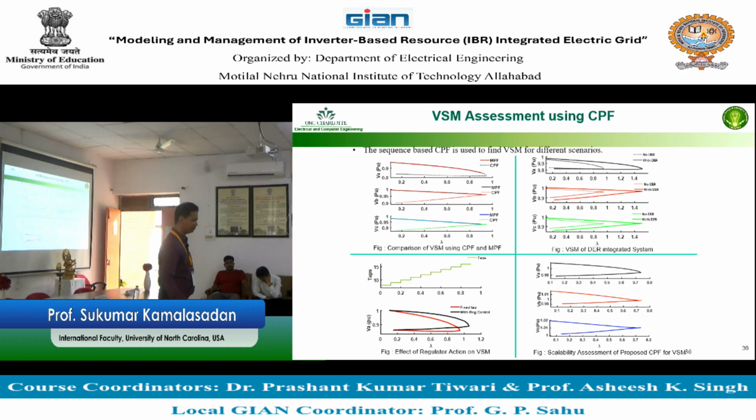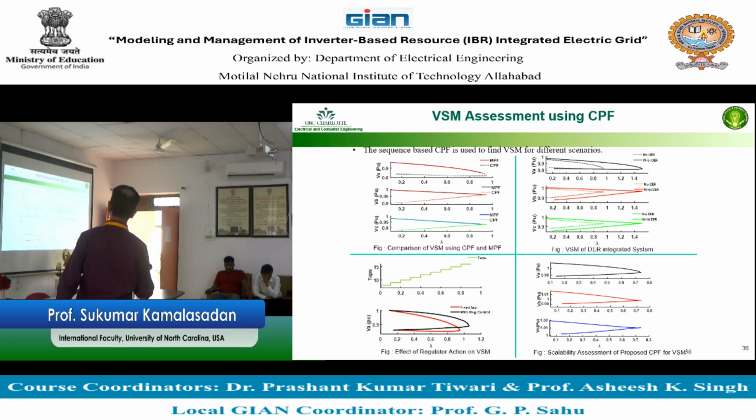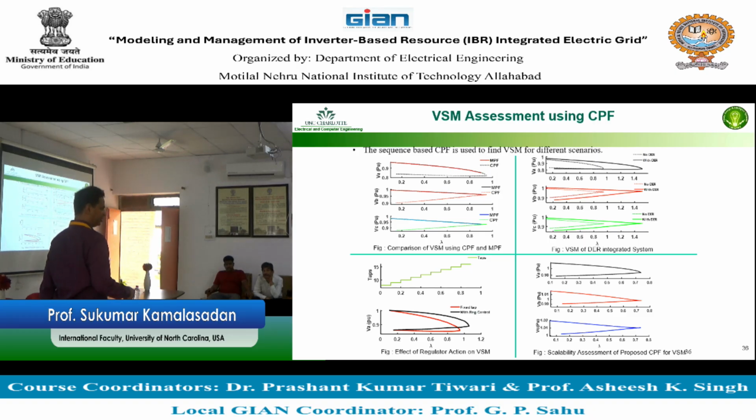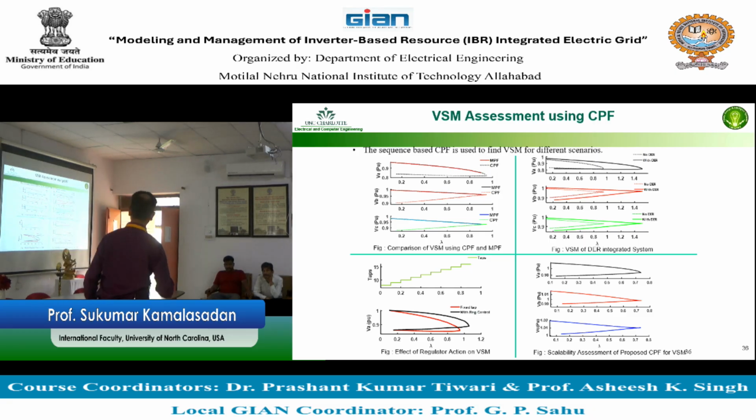If you run the power flow continuously, you may call that a multi-time series power flow, right? Continuation power flow is not that. Continuation power flow is a little trickier. You run the power flow multiple times and you can reach here, but to reach here you will need to do some tricks. That is done by continuation power flow. So I'm not going to go into continuation power flow.